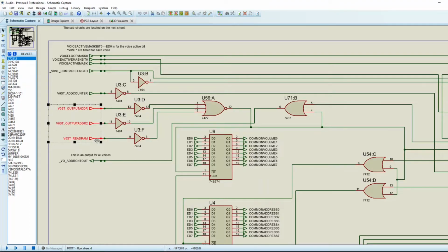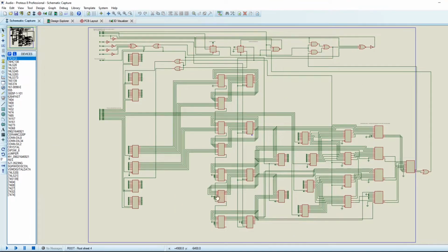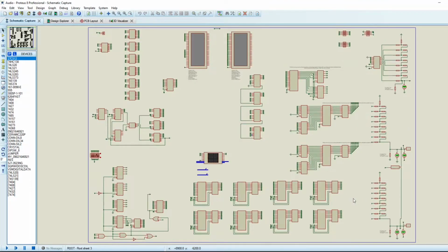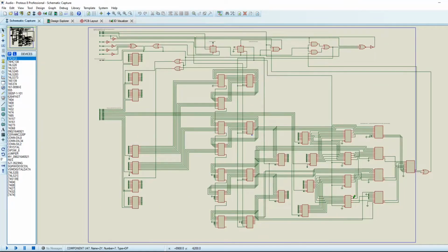And as we know, these state machine states are discrete. They don't occur in parallel with each other, they just occur in a very set sequence, so we know this logic diagram only accesses the common areas that were on the previous sheet strictly in sequence. So we know that we don't get any contention.